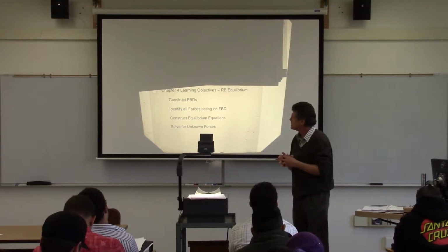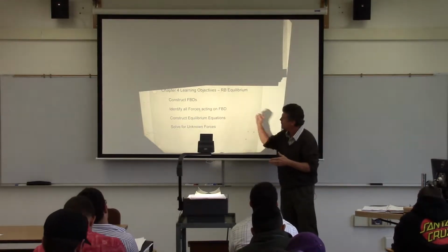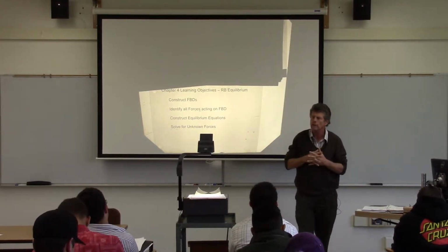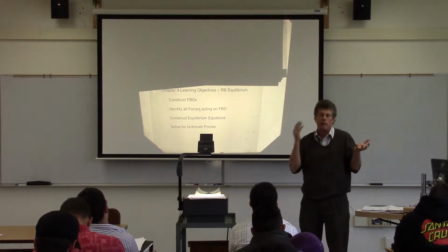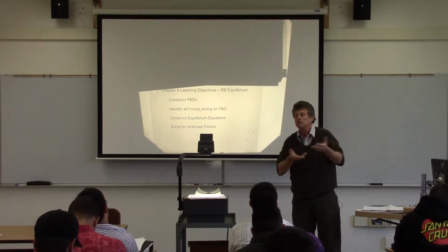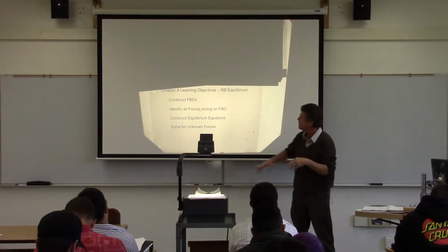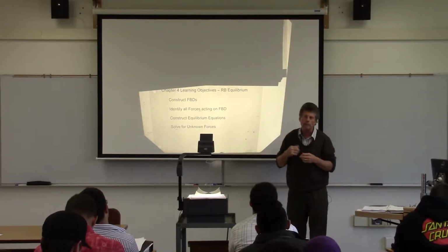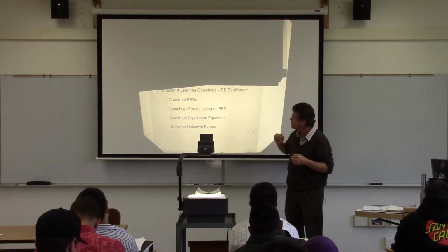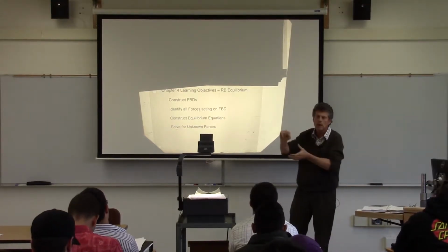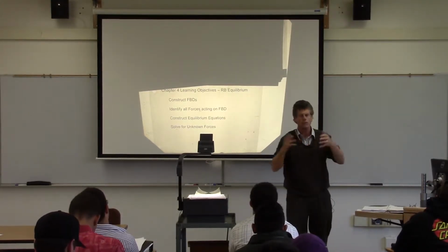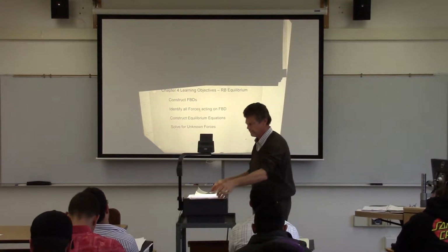So what we'll be doing is learning how to construct free body diagrams and identify the forces on a free body diagram, the most important step. If we don't identify all the forces, we'll get a wrong answer for sure. Once we have a proper free body diagram, we'll construct equilibrium equations, and then start solving for those unknown forces, and that's what statics is all about.